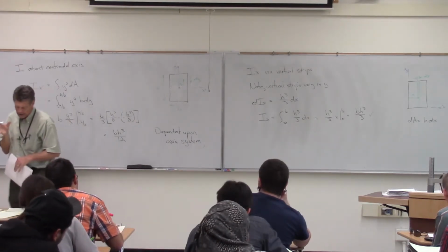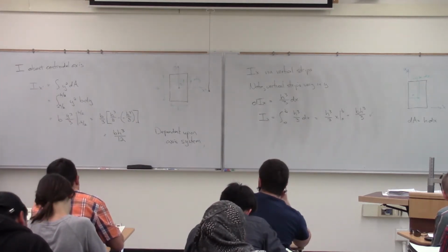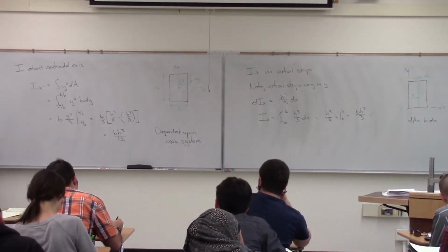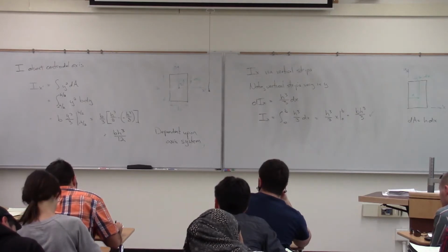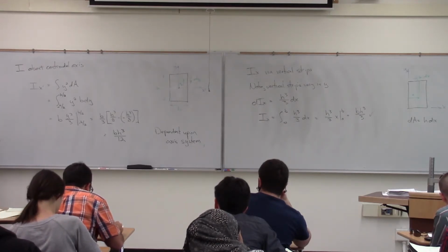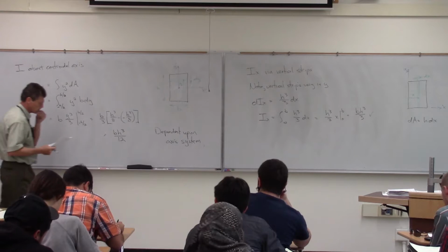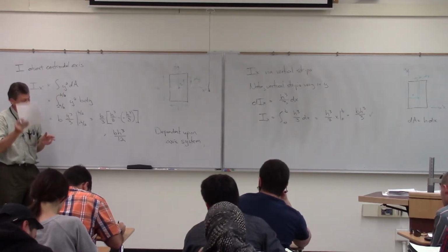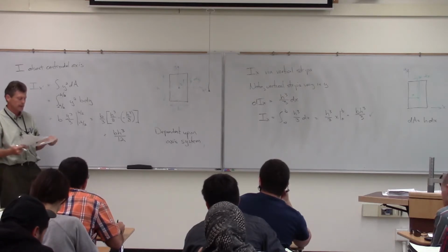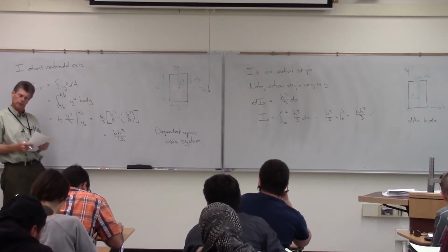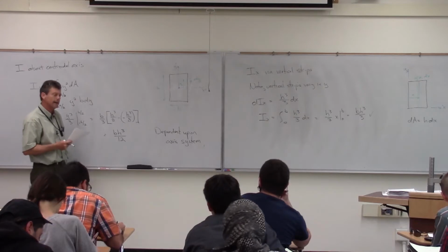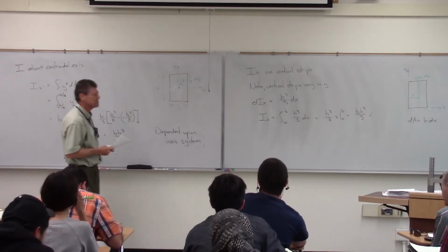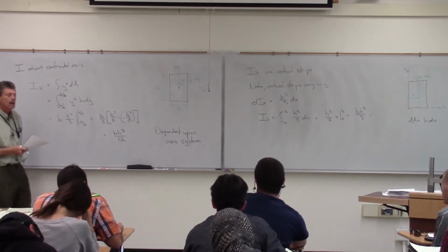We're going to be finding that depending on what axis system we're at, our number for our calculation of moment of inertia is going to be different. But it's always going to be smallest around the centroid. You're one step ahead of me there. Perfect. Yep. That's my little golden rule that I was going to put up at the end, and you beat me to it. Okay, you get extra points. Spoiler alert, yes. But that's a good point.